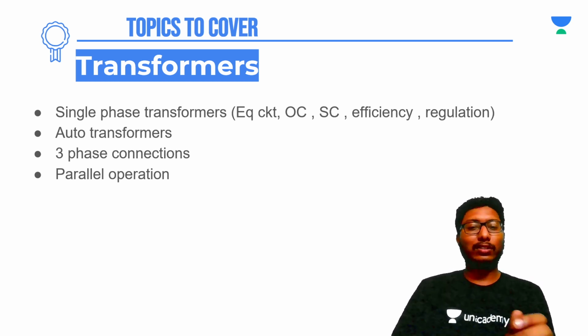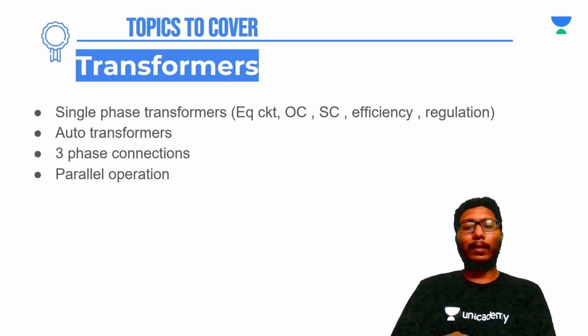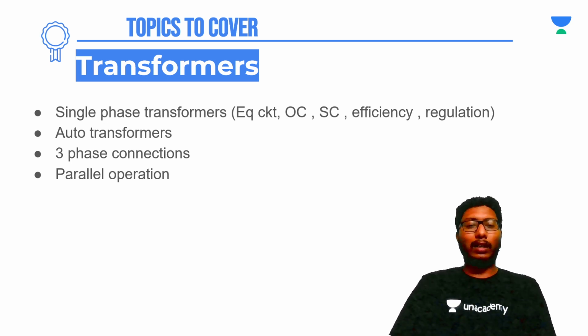So the equation will be similar to that of KVL. From there you can play with the problem, that is finding relative permeability of iron, or finding relative permeability of air, or finding the number of turns that should be there on the iron core, such that this amount of flux and flux density is achieved. So the basic thing is using KVL here, and making ampere turns equal to flux times reluctance. So from there you can get everything.